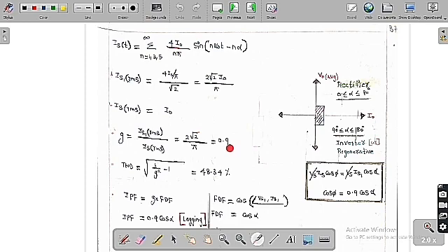It is a ratio of the RMS value of the fundamental source current to the RMS value of the overall source current. It is equal to 0.9 for this case. I have already told you THD. THD is equal to the square root of (1 by G) whole square minus 1. You know the value of G, substitute here, and if you solve this, we get 48.34%. So the distortion factor is equal to 0.9, whereas THD is equal to 48.34%, meaning this much amount of harmonics is present in the source current.